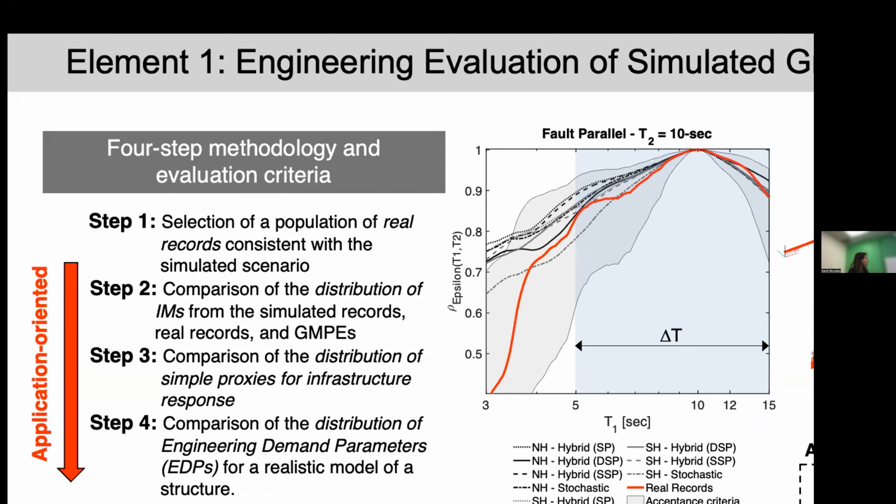This methodology, which we developed leveraging the collaboration with Norm Abrahamson, relies on the combined use of motion models and real records, and starts from a selection of a population of real records consistent with this scenario we're simulating, and then moves towards application-oriented types of analysis. And here, as an example, I'm showing the interperiod correlation for a conditioning period of 10 seconds, which corresponds to the fundamental period of the bridge deck in the out of plane direction, represented here.